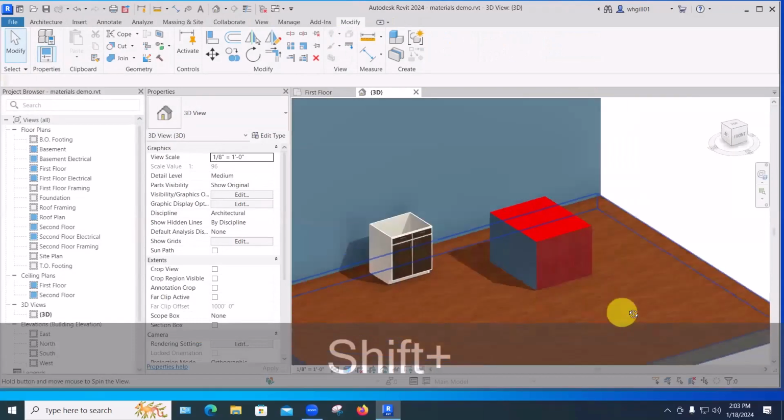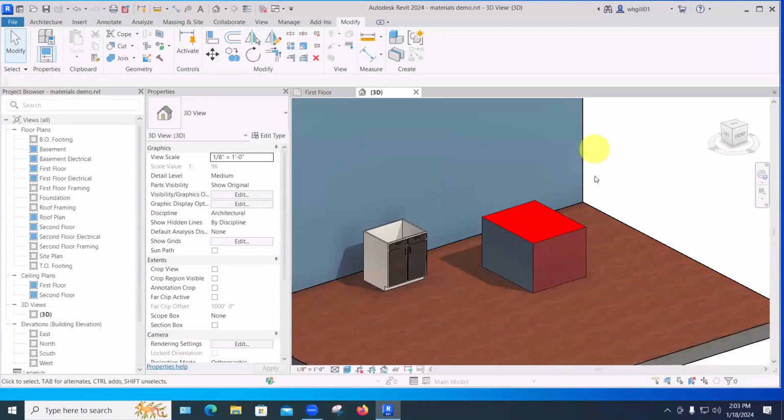So what it boils down to is that the two faces that I painted, those materials override whatever I give to the whole object. It's not like it all reverts back. And that way, if there's some oak inlay that I want to paint as oak, but change the base material to see how it works together, I can do that without worrying about erasing the special painted areas. Painted materials persist through changes in the base material of the object.